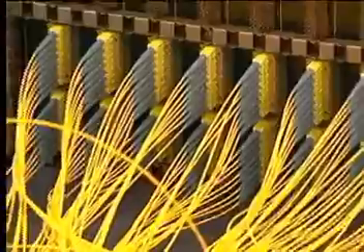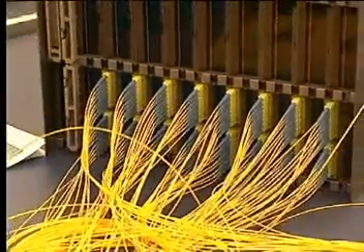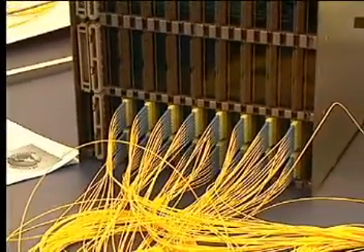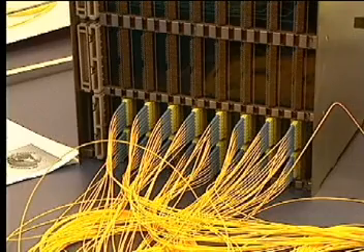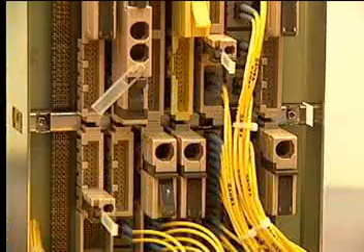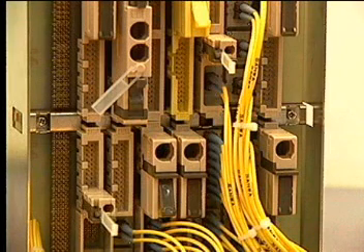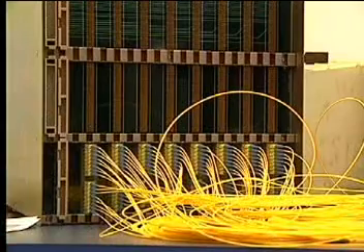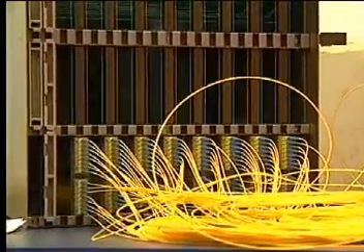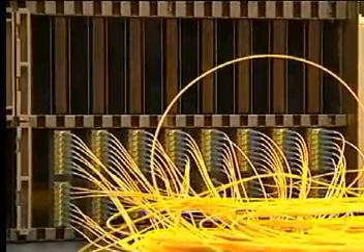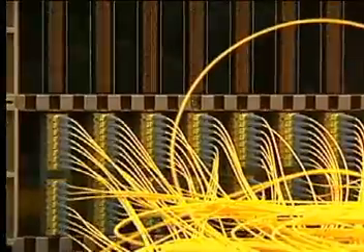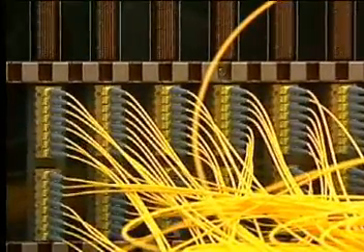In modern high-density fiber systems, much attention has been given to placing multiple transmit and receive functions on circuit cards for improved efficiency and to save valuable space. Thus, optical backplanes have appeared to meet the demand. Rack-mount circuit card cages are notorious places for the collection of dust and other contaminants. Although they are often difficult to access, optical backplanes and their corresponding card edge connectors require serious attention to cleanliness.